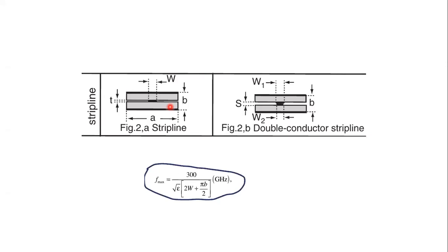And if it is done, then troubleshooting after the circuitry fails becomes difficult because the circuitry is available between the two dielectric materials, between the top dielectric material and the bottom dielectric material. So once a fault has occurred, you have to open it, remove it, then troubleshoot and fit it all back.